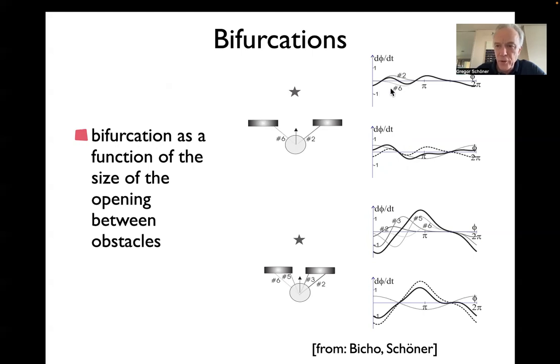In the obstacle contribution, you see the individual obstacles, the individual sensors contribute. So for instance, here you have a wide opening between two objects, and only sensor 2 and sensor 6 get a reading. They make repellers. Here's a repeller and there is a repeller.